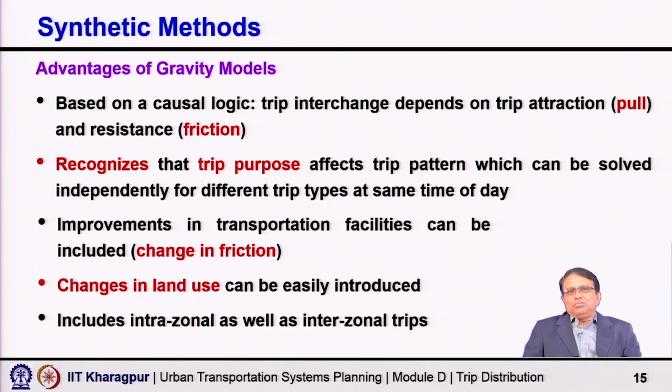Now, before we close this discussion, we have discussed the gravity model, what a gravity model is, singly constrained, doubly constrained, BPR calibration technique, how to apply the singly constrained model, how to do the balancing, and how to apply the doubly constrained model. We have explained it clearly, and with an example also we have shown you how you do it.